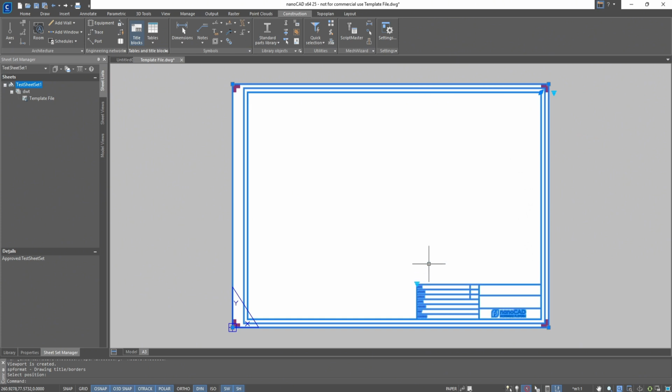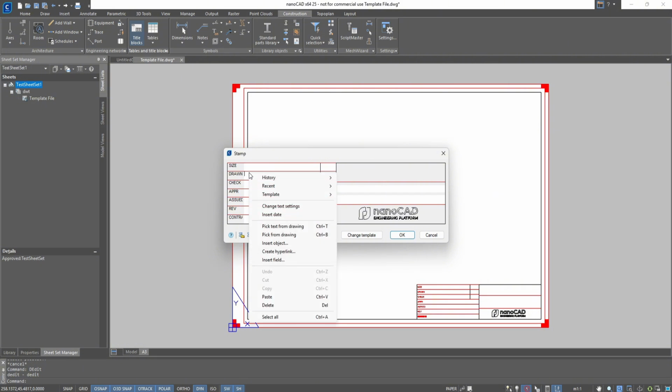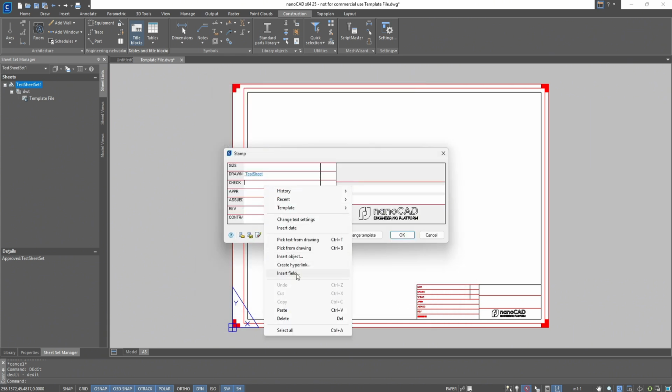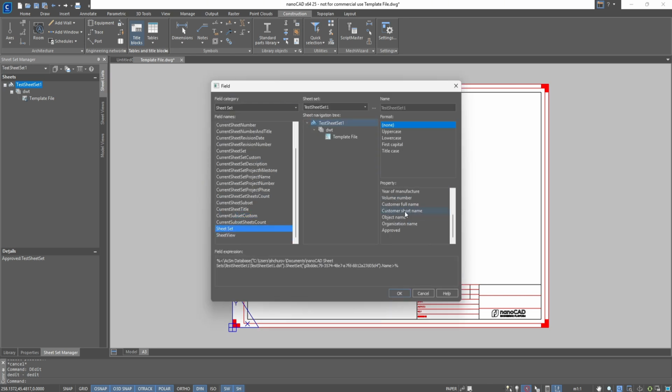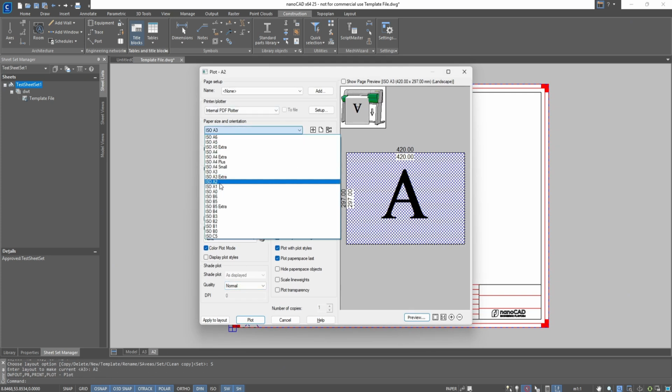Double-click on the stamp, going to its settings, and then right-click on the field to which we will add properties. Select the Insert Field option. In the Field category, Field Set, Sheet Set. For Group and Sheet, the created properties are stored in names that have custom in their name. And for Sheet Set, in the field of the same name in the property window. When creating new layouts, don't be worried that some fields are shown with a hash symbol. This will work correctly in the future.